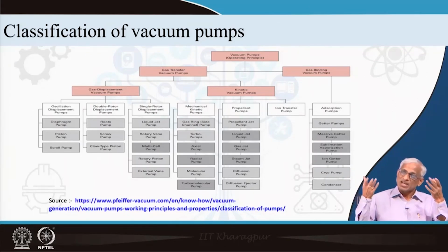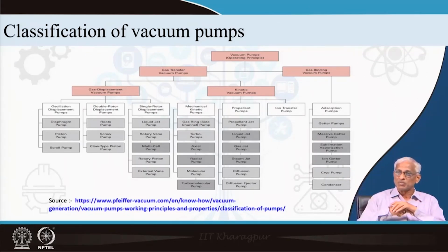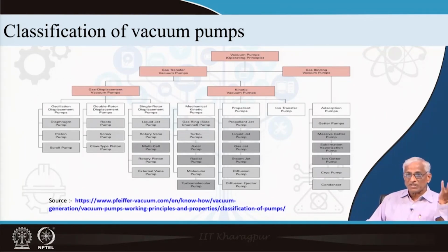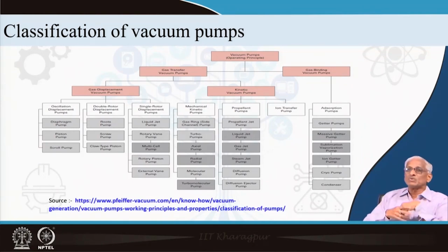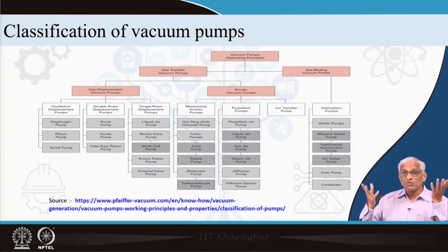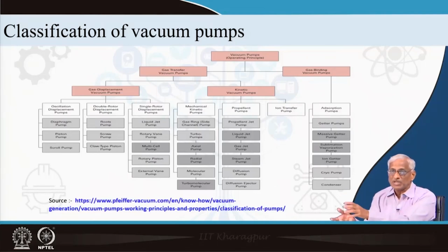Initially they were not coming as a part of vacuum technology. For example, Roots vacuum pump, Roots has made it as a Roots compressor, but today when you invert it, it has become a pump. And high speed turbines which are used in aeronautical application, they never thought that such a high speed can be used to produce ultra high vacuum here. Okay. A mechanical thing, a turbine rotating at very high speed for 60,000, 70,000 RPM, a fan rotates only hardly 1500 RPM. Such a beautiful bearings are developed, such high speed turbines are being developed. This technology has been converted as a pump in vacuum technology.